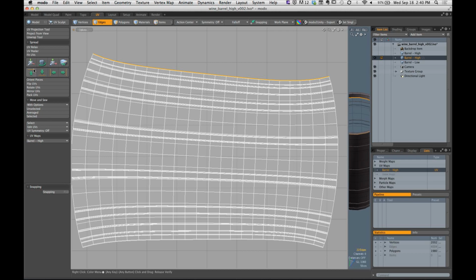If you've been wondering what these big green arrows are over in the UV toolbar, these are alignment tools, and what this is going to do is examine every single vertex along the selected edge and align them to a common point. So what is that common point? How does the computer understand where within our V axis to place these edges?